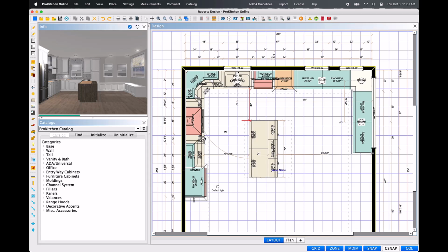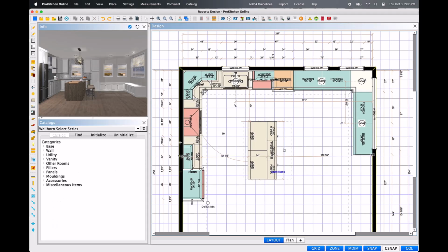I will need to repeat the process in relation to the additional perimeter wall. Grab the Line-to-Line tool with a left click. Place the mouse at the front of a base cabinet on the perimeter wall and left-click to start. Then drag the mouse to the face of a cabinet on the island and left-click again to secure. Select the dimension line, activate the length field, type the required distance, and tap the Enter key on the keyboard. Now the island is 100% placed precisely in the design for the installers to follow.